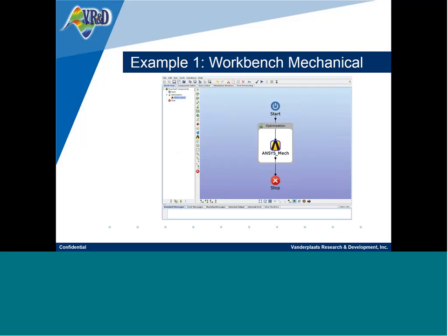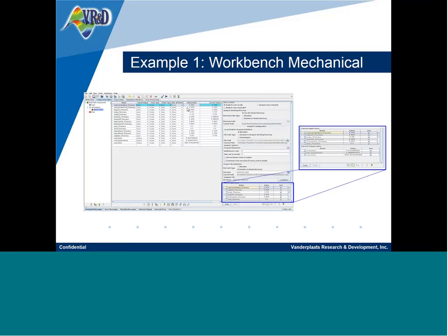So here is how the workflow looks for this problem. You select the ANSYS component in the model tree and click the component editor. It will show the property editor. Here, for this problem, all the input parameters are extracted and the output is in the output data table.